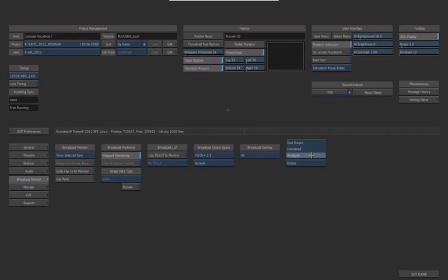That dual output allows us to output two full resolution eyes, so the left eye down your A-link HD-SDI in 422, and then your B-link SDI would be that right eye, full resolution. So this is appropriate for sending to a monitor that can support two full resolution eyes, or indeed a projector.